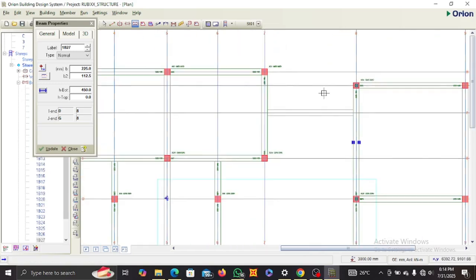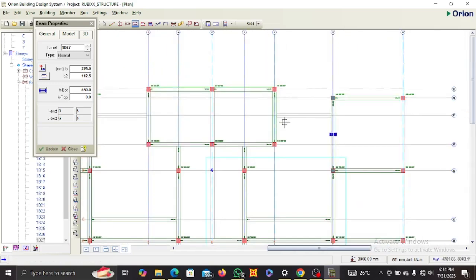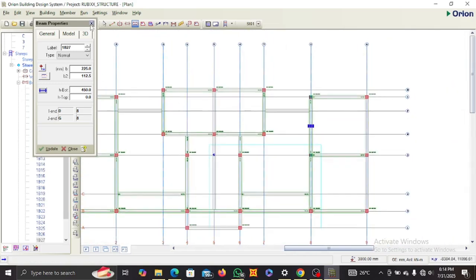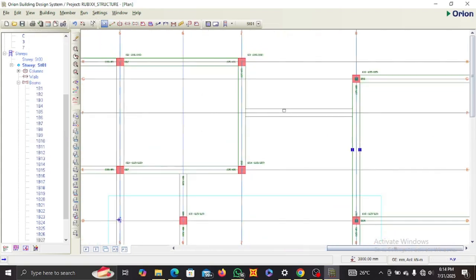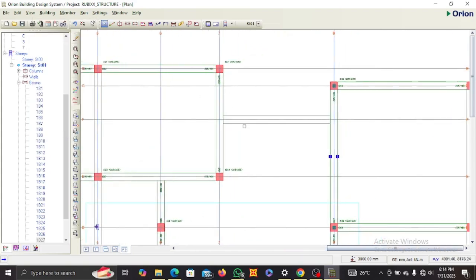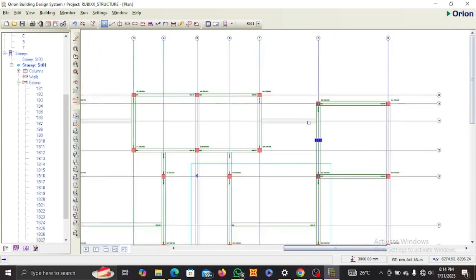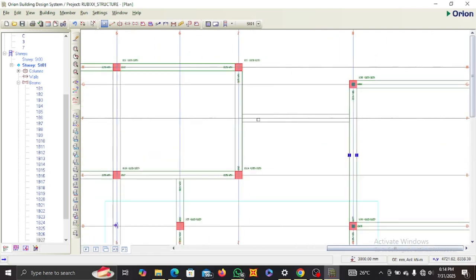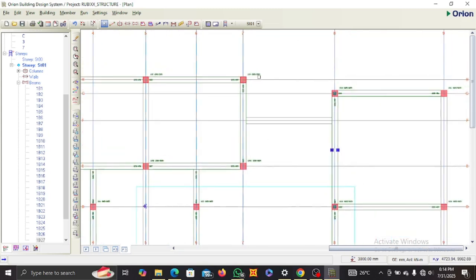And also note, if you notice, let me just stop there for now. If you notice, I inserted, you realize that this other beam here, this other reference joint, there's going to be a beam here. You realize that I did not start inputting this particular beam. Why? Because these softwares are done in such a way that the first beams you place are going to be your primary beams, right? While the next ones are going to be secondary beams.